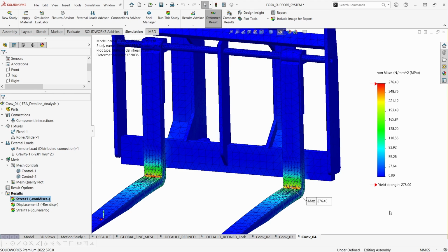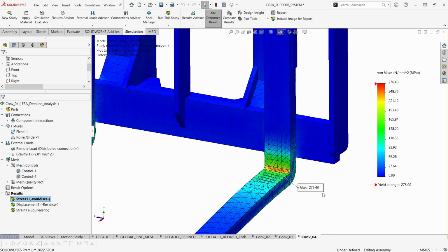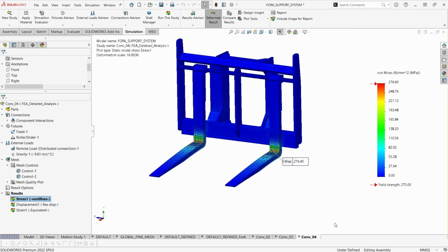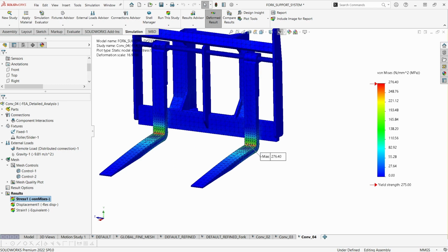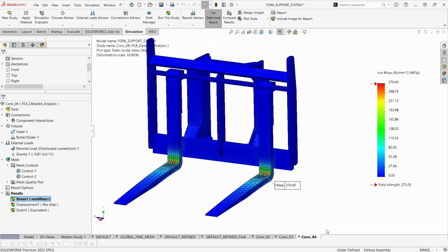I need to say that the values are not increasing so sharply, and this indicates that we are achieving a good behavior in our detailed zone. However, as we didn't achieve a constant number yet, we need to continue reducing the mesh size until we achieve convergence. I don't want to bore you, so I will prepare all of them and show you the results. See you now.